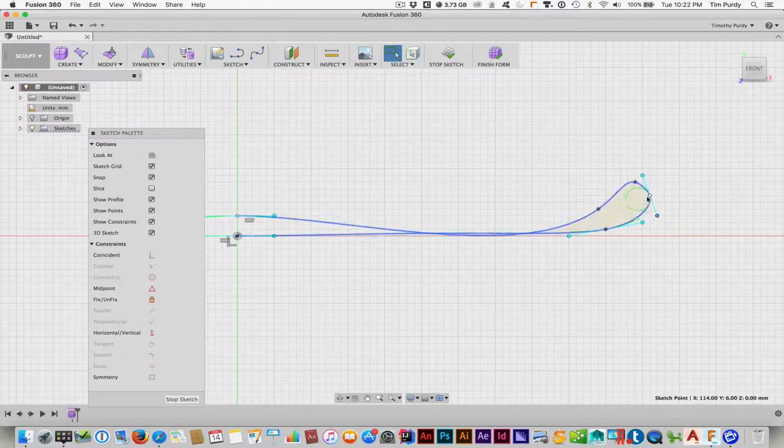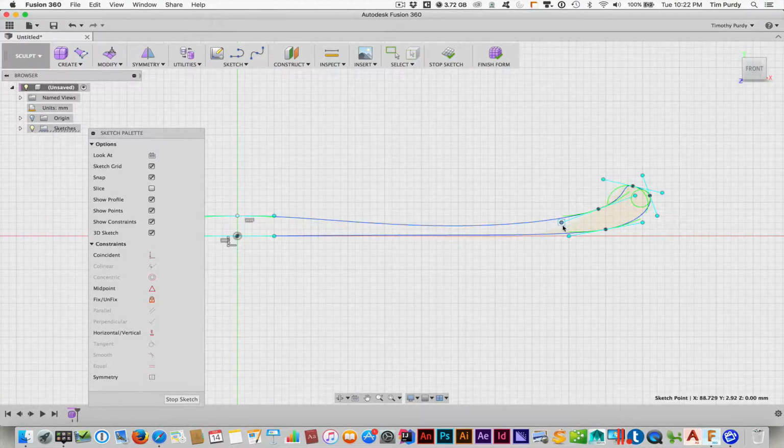So a lot of times you'll get that as you pull this. Basically it's showing you the inscribed circle, what they call the actual curvature. So this is indicating it's really tight there. Click on this one and start sculpting that. You can see we can make it tighter. We can visualize and make it about the same, which I'll do. Okay, and let's pick this point and then try to sculpt this handle.